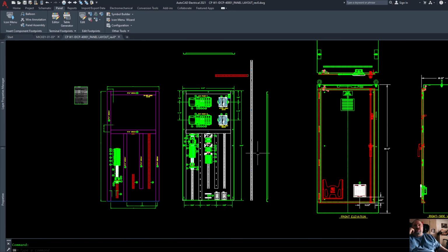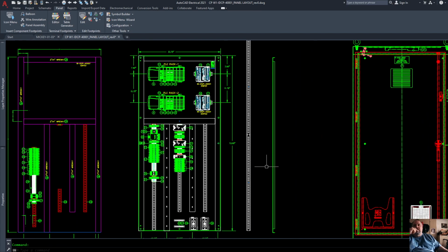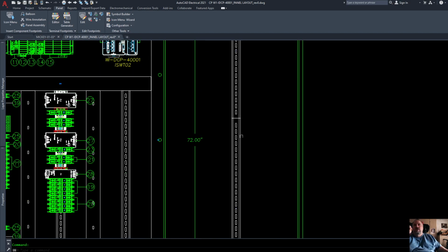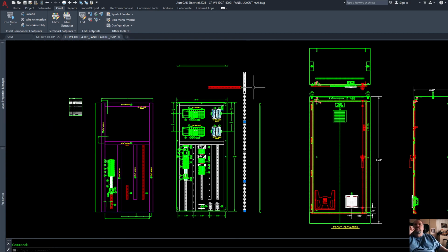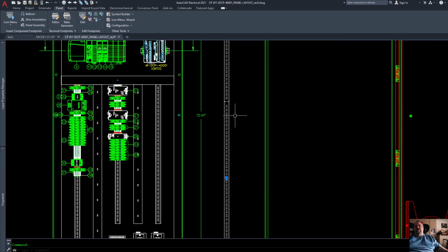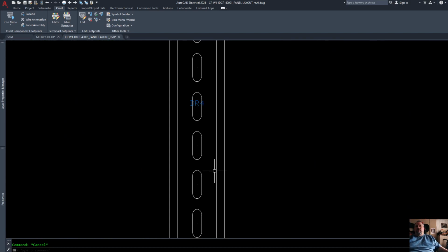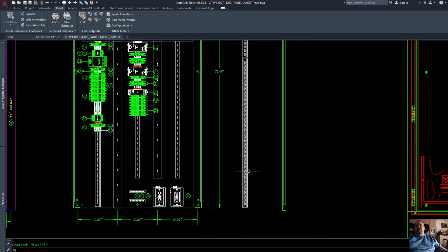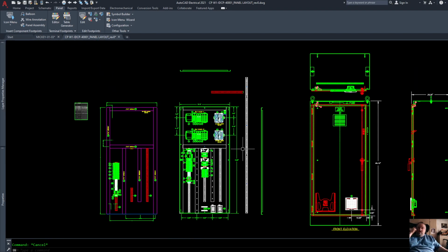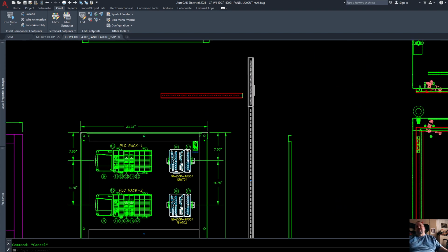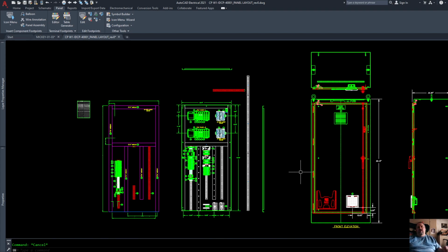Now it actually inserted all the pieces you need, because AutoCAD knows how long it is, because I tell it how long it is. And these are actually 3 pieces of Dinrail. And they're the correct size. And all the holes are lined up correctly with the real world. The good thing about this is the old way we did it, you would install it and then you'd have to delete all the pieces you weren't using and all that stuff. So with this, you don't.